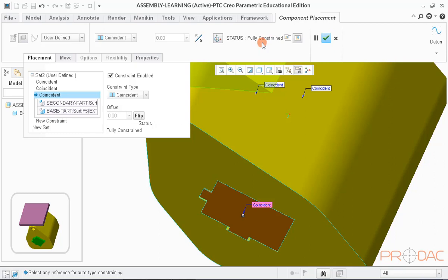But as per final assembly requirement, this path surface needs little offset. We can see this offset in the bottom left picture showing the final assembly condition. We'll be providing the offset of 5 mm by choosing the constraint type distance.